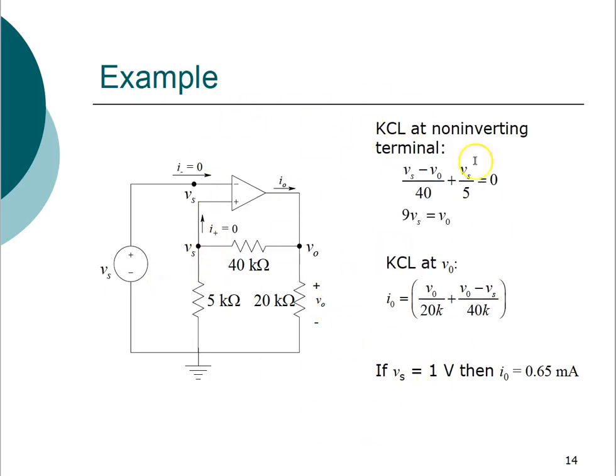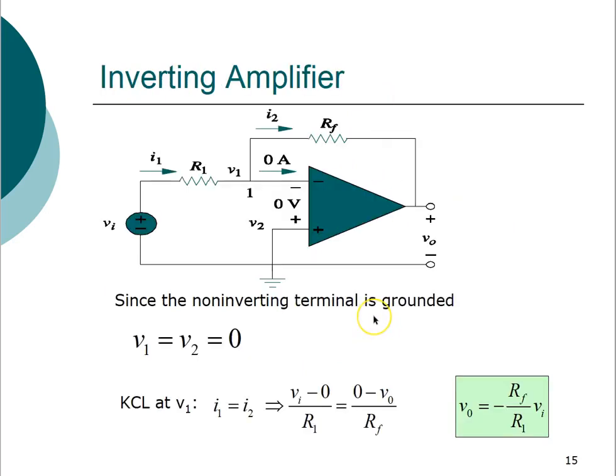But the only difference here is that we considered the properties of the operational amplifier. And then we discussed the inverting op-amp, where you provide the supply to the inverting side, and at the output side you get the inverted signal when compared to the input. So whatever signal you give here, you get the inverted signal at the output. And this was the very important equation to find the output voltage in case of an inverting op-amp.